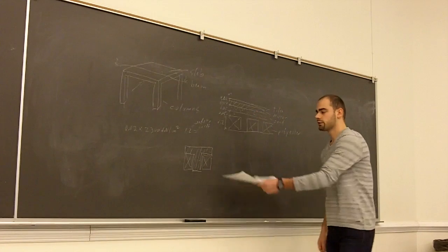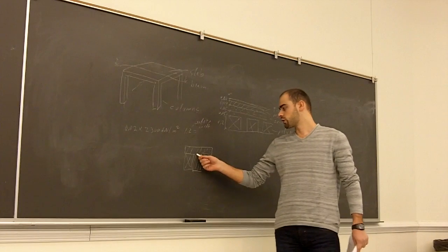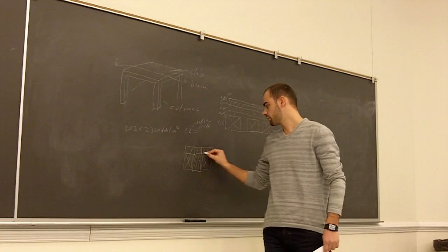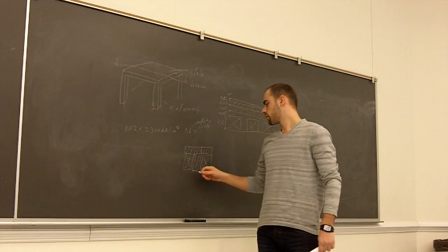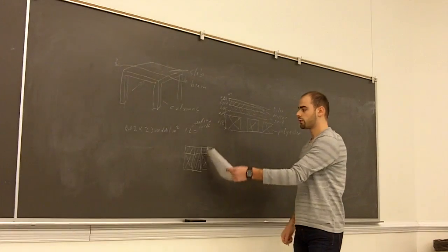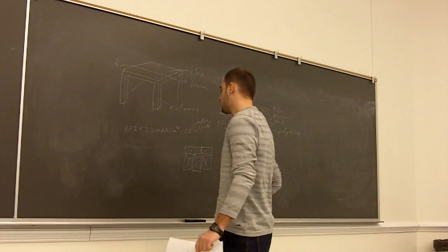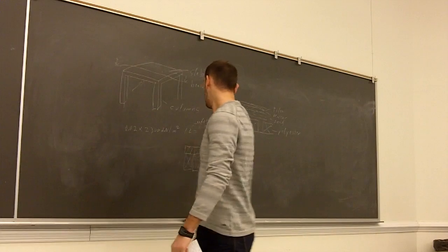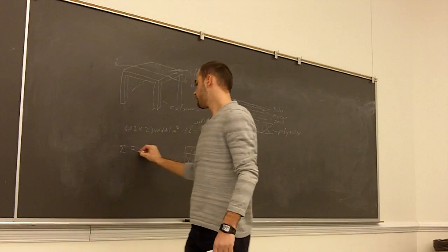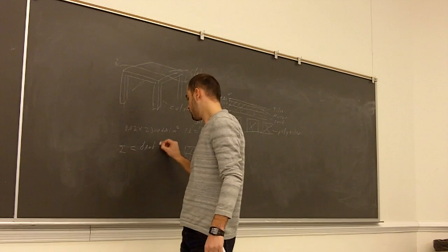So to calculate the load of the slab, we calculate the concrete with the T section, we divide it in square areas, and then we calculate the load of the bricks, and we sum both these loads, and we take the sum as the load of all the slab. After having all the loads here, we take a sum, and this will be the dead load of our slab.